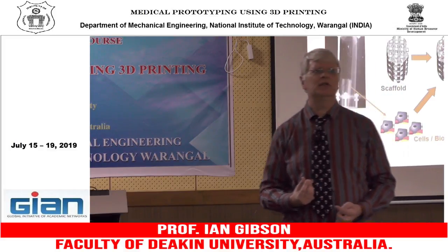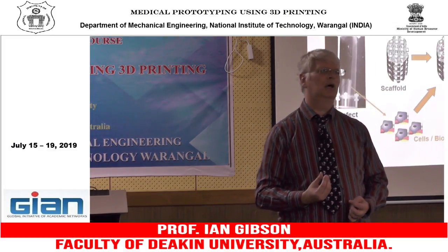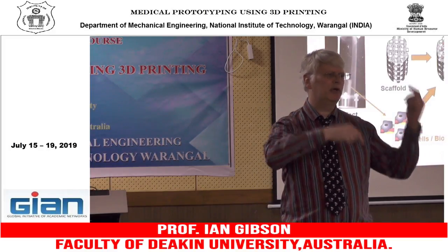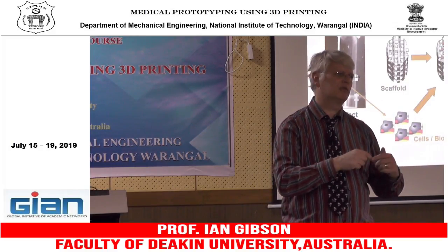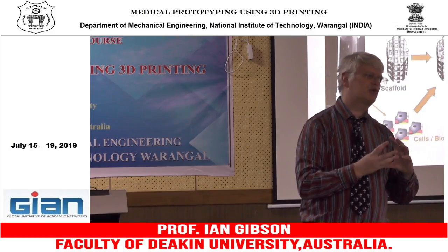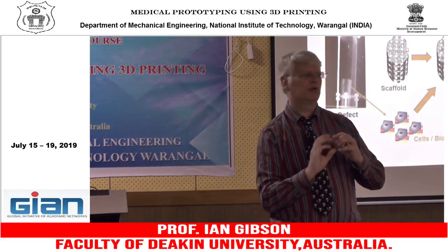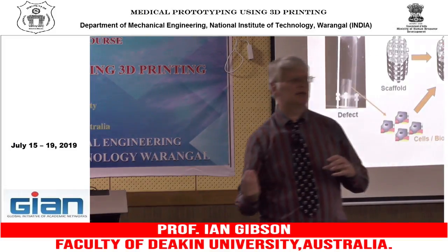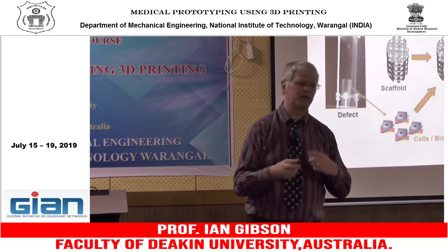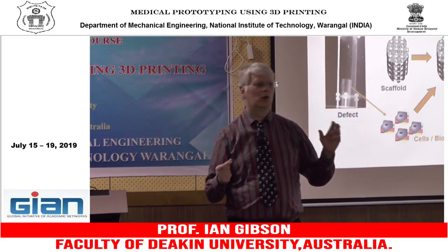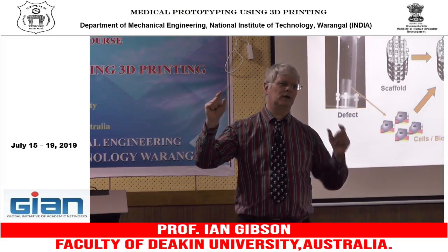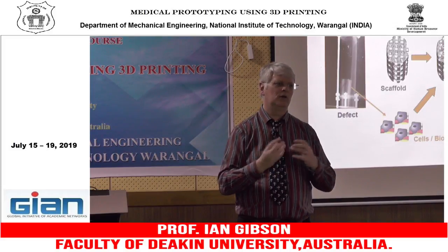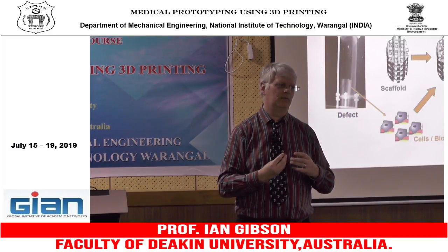We didn't preheat the material. We pre-blended it. We didn't just load in powder and material simultaneously. We used a twin screw mixer to create powder particles which were already blended. And the other thing is that sometimes we also experimented. If you've got a ceramic and a polymer and you mix them together, they don't bond together.